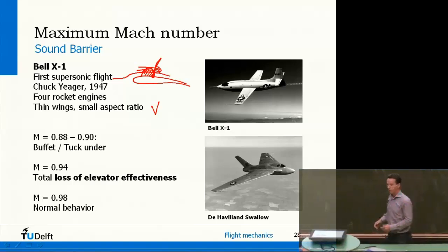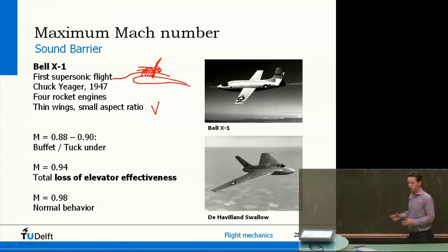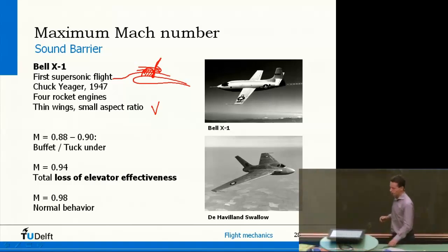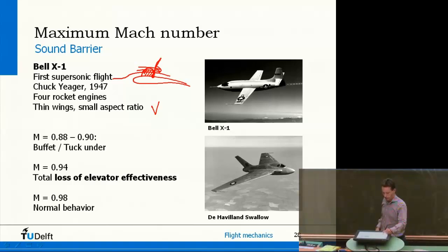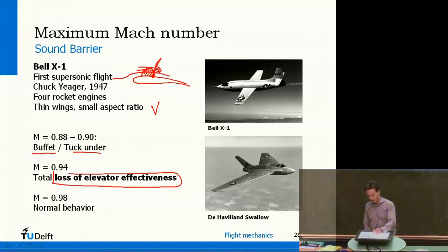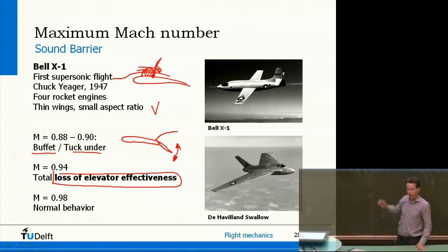But what also happens is that if you start to go very fast, then the point at which the lift is acting on the plane gradually shifts a little bit. So what you will start to feel if you go very fast is buffeting, and the nose might go up, it might go down, simply due to the fact that the lift of the aircraft acts at a different point. But what may be even more important is something else, and that is, of course, at the back of the plane you have the elevator, and you want to deflect that up and down in order to control yourself. Now, if you fly at very high speeds, then at some point a deflection downwards could actually cause a shock wave over here, which means that in some cases, without going into the details, these Mach effects can make the plane become uncontrollable.